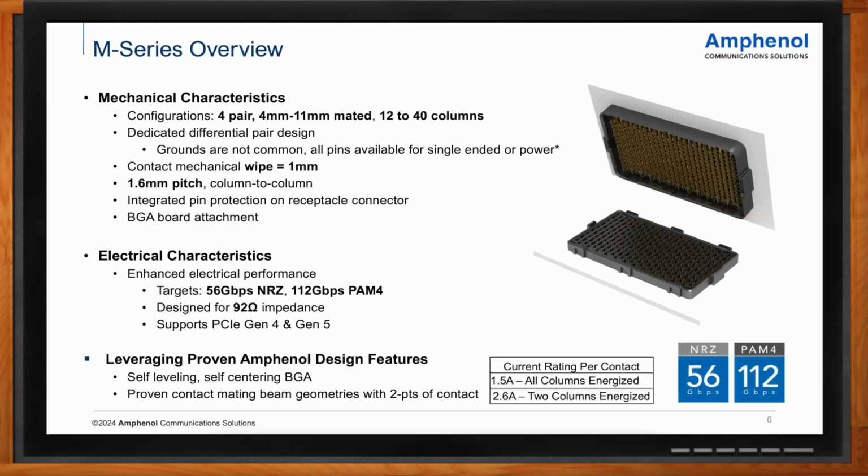M series leverages MEGArray, and it does that in the contact interface design, but most importantly, it does it at the BGA level, which is the solder sphere. It's how the connector connects to the PCB, and that's a very important piece of technology for us. We've taken MEGArray and taken the opportunity to build in some additional features for various reasons. Sometimes it's for signaling. We added a little bit of wipe. One of the features we built in was just adding this protective layer on the receptacle.